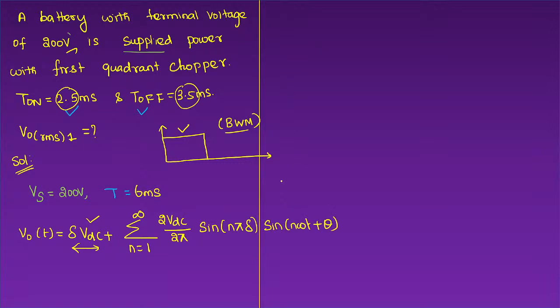Don't think too much, sir. I found this formula only in the inverter. How can you write the same formula here? Because here also I am doing the same on the output side. I am trying to express the trigonometric Fourier expansion for the rectangular waveform. Fine, sir. Now, which one is called fundamental? Output fundamental in the sense at n equal to 1, that is called the fundamental expression.